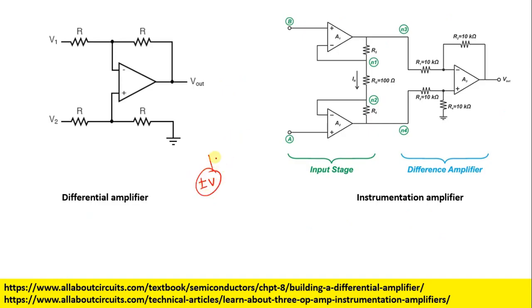So this is your, say, 10 ohms, and that is your E. So when you have this, the voltage drop will be quite minimal across this resistance. That means we are losing the voltage information. However, when we have this 1 giga ohms, the voltage drop will be quite large. Okay, so you will be able to measure whatever source voltage you have.